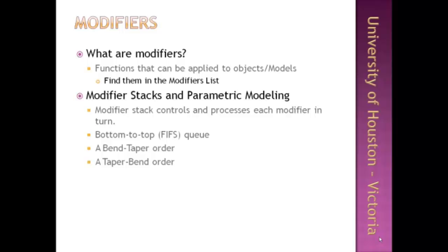You can even copy, paste, and cut and paste modifiers within the same object or among different objects. Right-click on a modifier, and from the pop-up menu you can choose to cut, copy, paste, or perform other operations on your modifiers. We'll see an example of that in a little bit.